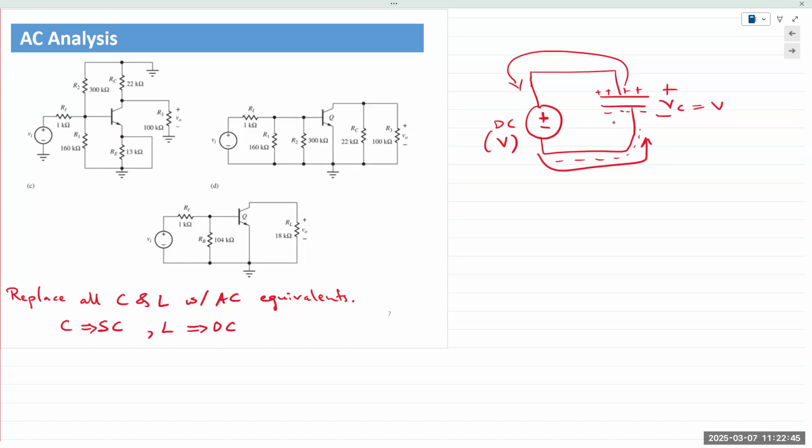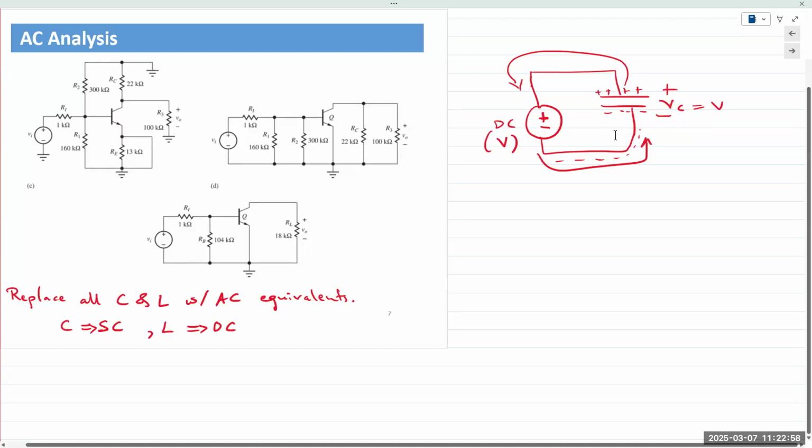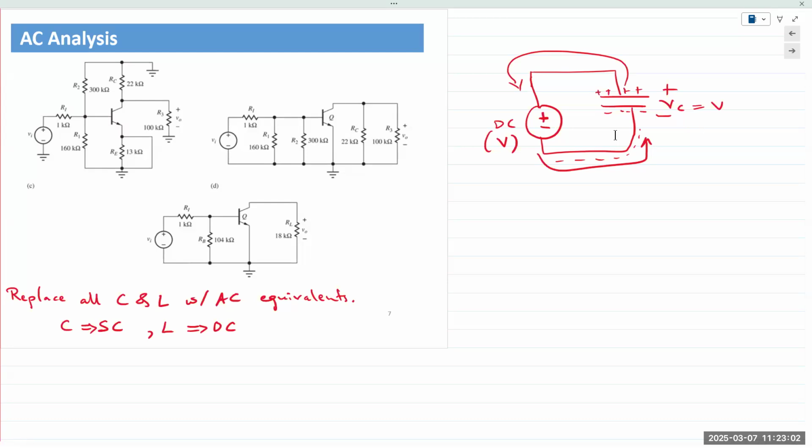So electrons stop flowing in the circuit. The capacitor has reached full charge and behaves like an open circuit. So it's not as if for AC it must charge. It is because it is charging that we model it as an open and short circuit. Does that make sense?